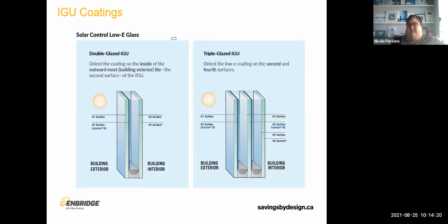But then in order to verify that that's been met, you end up needing to do air tightness testing of the actual building. Again, which is something that is becoming more common in the industry. It is something that Toronto Green Standard is introducing, but it's still new. It's not commonplace.